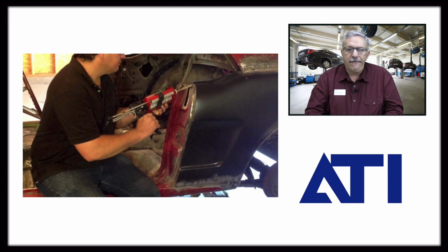You must identify from the manufacturer if they authorize the use of adhesives in their repair processes. It's very specific by vehicle whether you can or can't use it. There is some case law that's being developed right now in Texas that is a huge issue, where someone used an adhesive bonding process that neither the adhesive manufacturer nor the OEM recognized for that vehicle. And it's becoming an issue that the shop has to deal with after the fact. And it's getting to be a long process for them. Don't put yourself in that position.